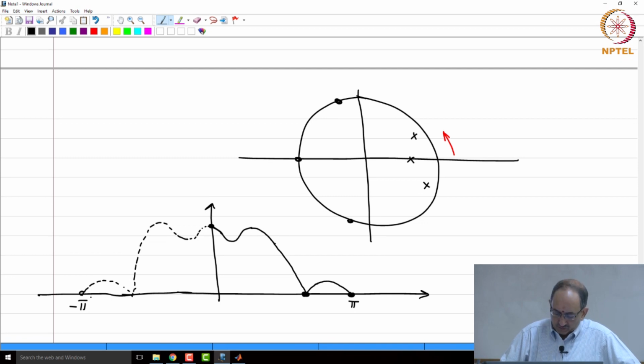One thing that I have assumed here is each pole is close enough such that when you are near that pole, it causes an individual bump in the frequency response. If you did not have this information, you cannot draw this plot. The other thing that I have implicitly assumed is all the heights are exactly the same.